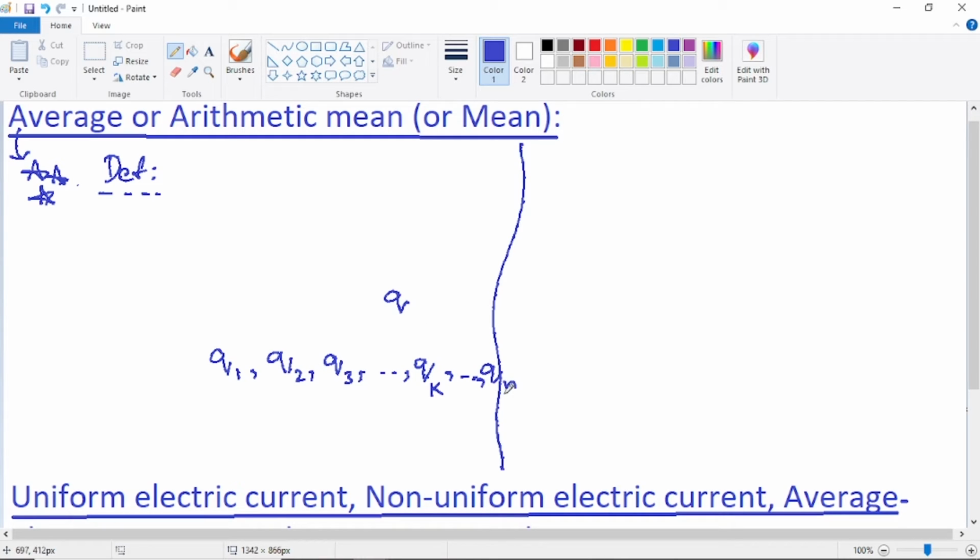All these n values differ because of various reasons, like errors in the process of measurement, error in the instrument itself, or error in the object itself. When we're measuring a cylinder with a vernier caliper, the cylinder can have slight deformities, so along different lines parallel to its axis, slightly different values can come. Then, in order to remove all these errors, what is the usual process? The average of all these values is taken.